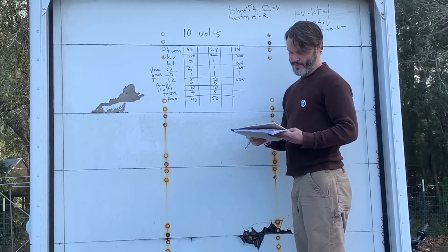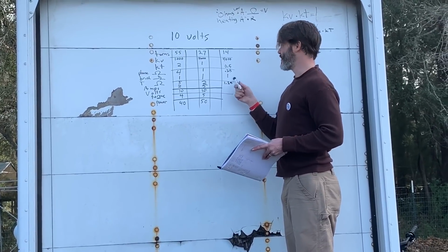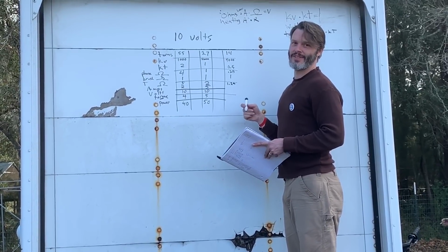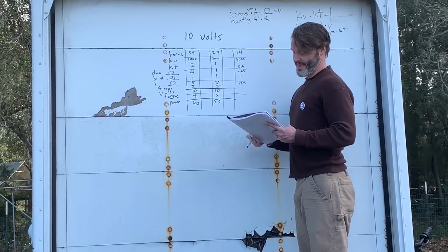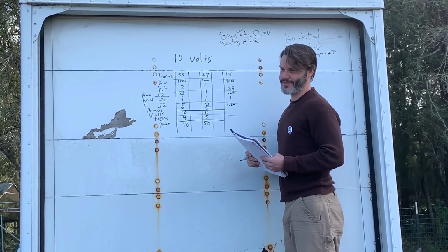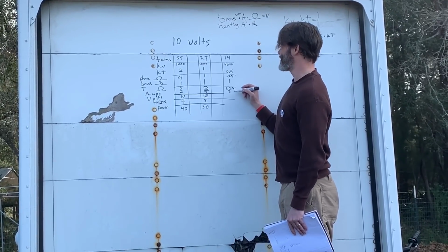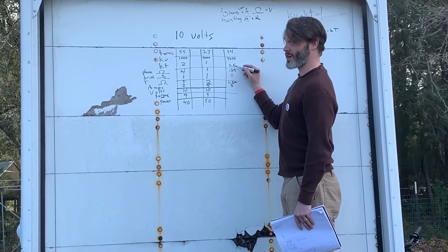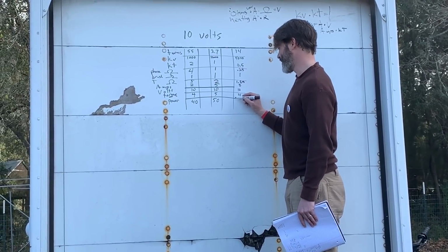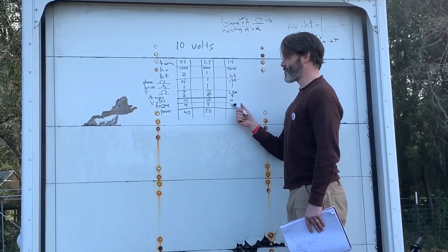Our amps, let's see if I did calculate that. I did not calculate that yet. So can anybody help me out here? We got 10 divided by 1.25. Buddy, I think it's gonna be 8. I think. Seems about right. Yeah, 8. Double check? All right, 8. So 8 amps. 8 times 0.5 for our torque constant up here is 4. And we're still on 10 volts here. So 4. Look at that. We went in the other direction. We went faster and we lost torque again.